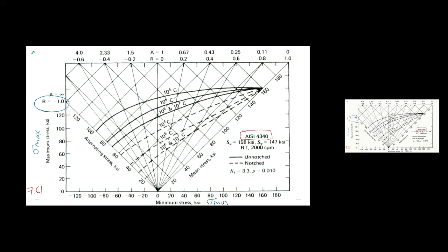And then if we go up and along the top, then R goes from -1 all the way up and around to 1.0 at the opposite extreme up at the top, okay? And so we could follow all of these locations around the top down to the 0 point, right? And if we knew what R was, we could just follow those lines and then look over at what is our allowable alternating stress and mean stress for different lifetimes.